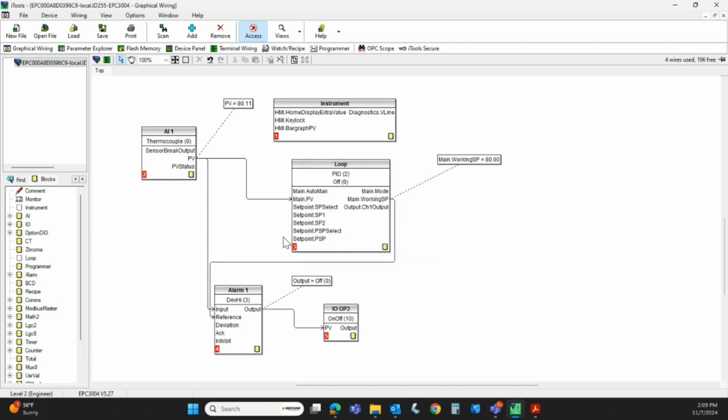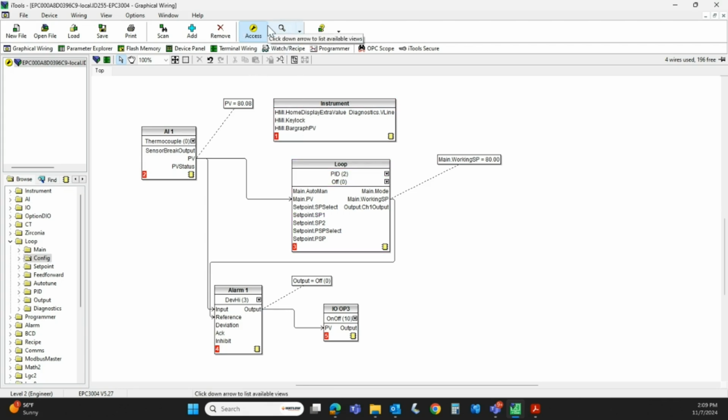So your password is unique, and on the initial power up of the instrument, it will have prompted you to generate a passcode. Don't forget that. It's the only way you can log into engineering mode. If you happen to have forgotten it, there's a whole other video on how to reset that. Anyway, the other caution here is when you're in access mode, as a safety, the controller's outputs are disabled, so we no longer control the process.